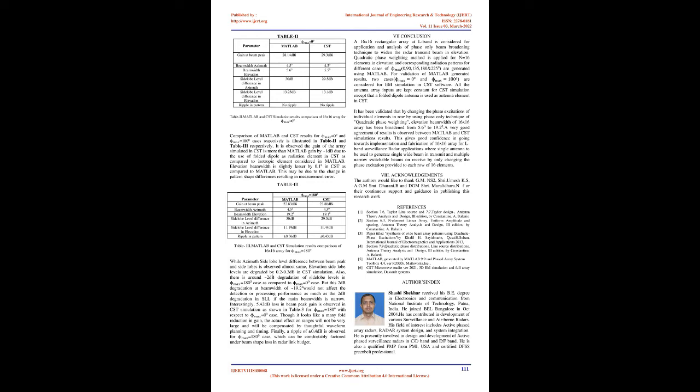Directivity has reduced from 28.14 dBi for φmax equals 0° to 22.83 dBi for φmax equals 180° case. Interestingly, the beam width has increased from 4.5° to 19.2°. It can also be found that pattern ripples are observed for φmax equals 180° and 225°. Typically, a pattern variation of plus or minus 0.3 dB is observed for φmax equals 180° case. Generally, a pattern variation of plus or minus 1 dB is accounted in radar's link budget. So, selection of optimal φmax for beam broadening depends on gain, BW requirements and tolerance to ripple.